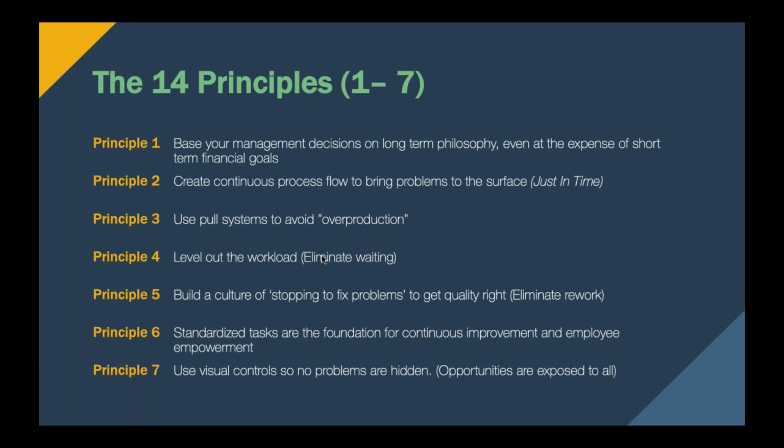What this means is that when you are doing a job, if you take one step at a time and finish one piece and then do the next piece and then do the next piece, problems with the process will surface and be more diagnosable than if you prep the panels and install the racking and are doing all of the pieces all at once. And so it is useful to do things in a continuous flow, to find the problems, diagnose them, and prevent them in the future, which is at the core of quality.